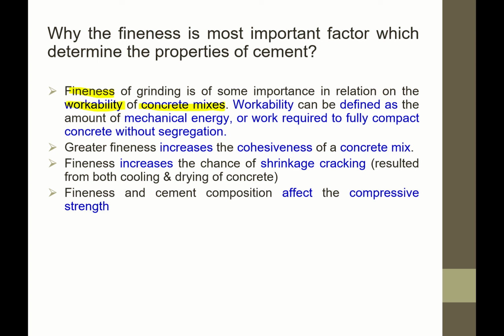You can explain this in terms of the amount of mechanical energy. If you have the best quality of cement, we can expect less work required to fully compact concrete without segregation, so you have a better concrete mix. The end product of concrete is better with good quality cement.